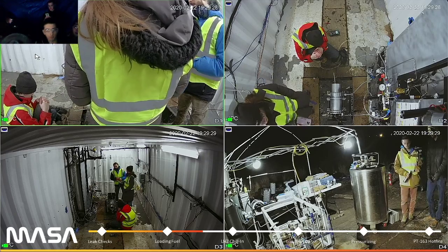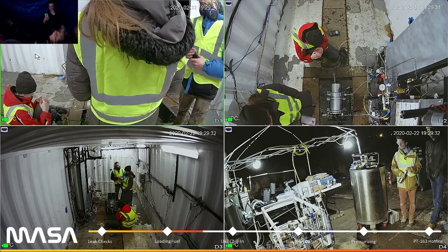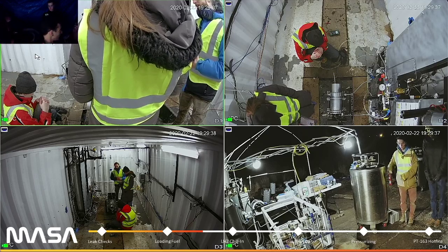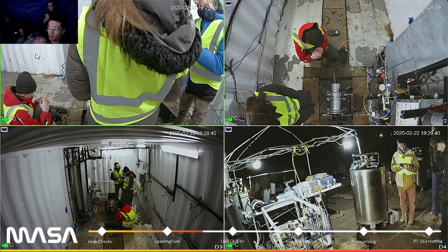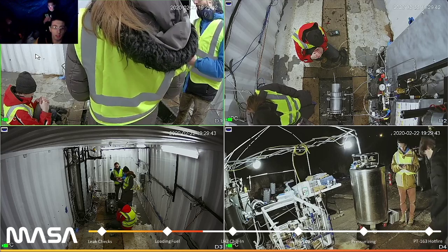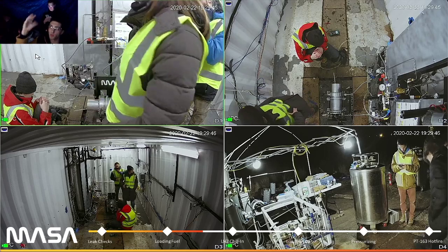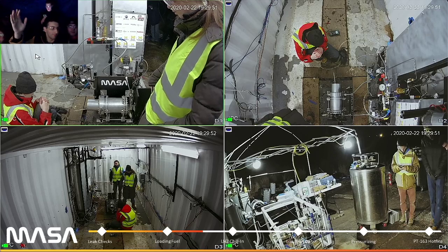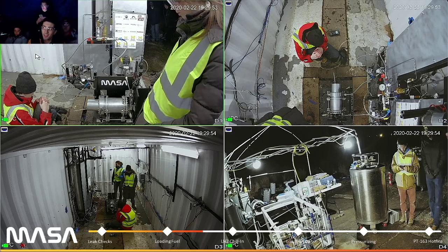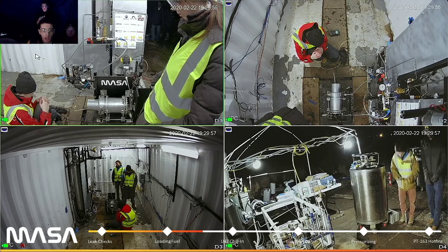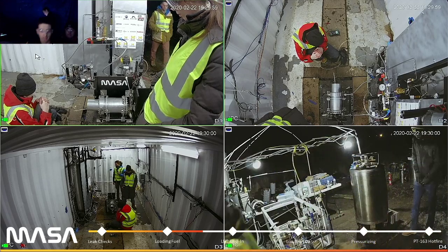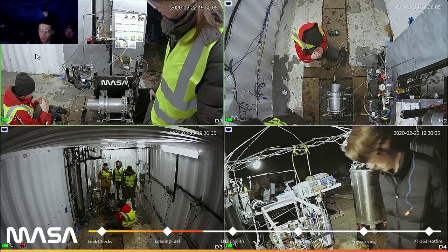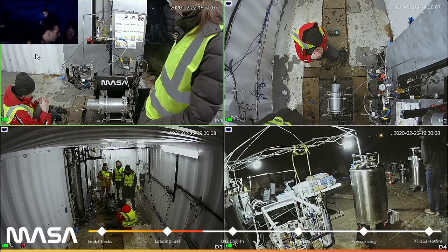So, Andrew, where are we at, and what have we been doing all day? So we did some leak checks for our system, to make sure none of our fittings were leaking. Then we loaded in our fuel, and now we are at our LN2 chill-in, which I already talked about. We're making pretty decent time. We expect possibly to be able to hot fire, but when do you think maybe?